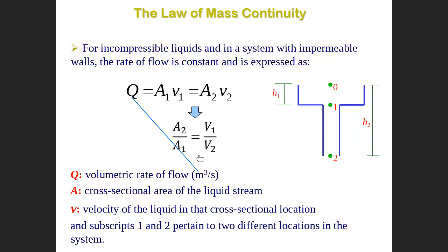Okay. Right, so if we know the velocity at point 2 from the previous step, by using the Bernoulli equation that satisfies the condition of avoiding aspiration, and we know the area here, then VA equals Q, the flow rate. As I told you, the flow rate is constant. So we're pouring liquid here at a certain flow rate. As we know the area and the velocity here, we can calculate the flow rate, in cubic meters per second.